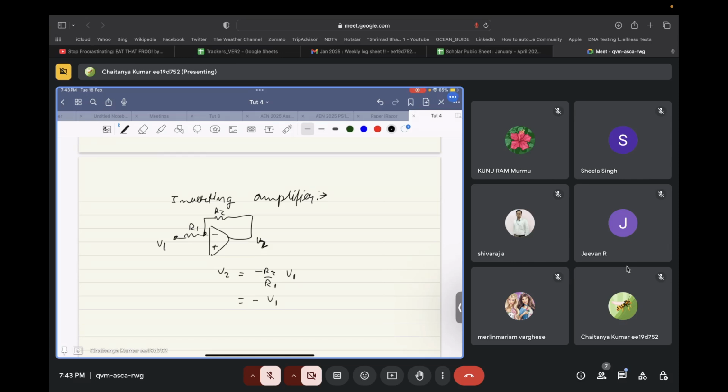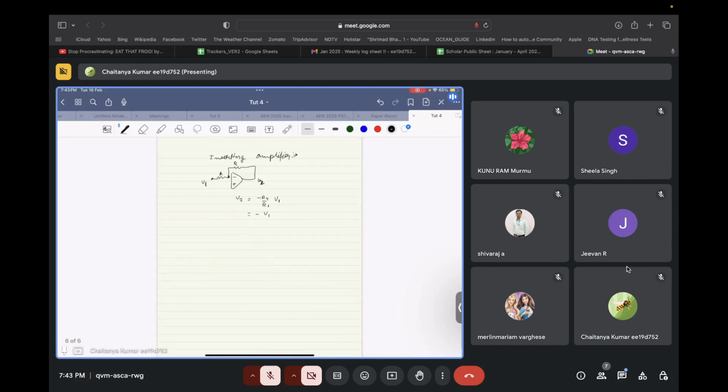Correct? So if the resistance of the input and feedback resistors are made the same, then you can get an inversion. So the final circuit over here will look something like this. You will have R, you have some capacitance C, you had a resistance R, and how did you make your inductor?